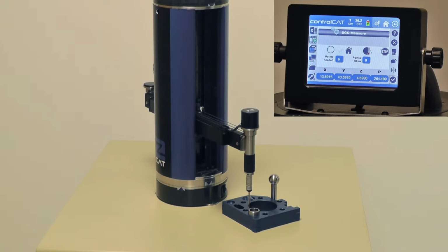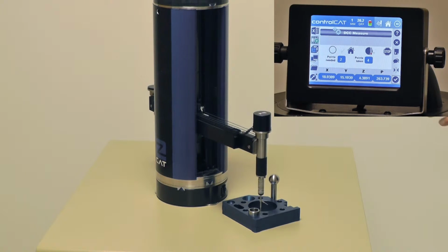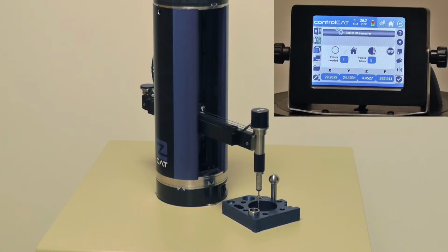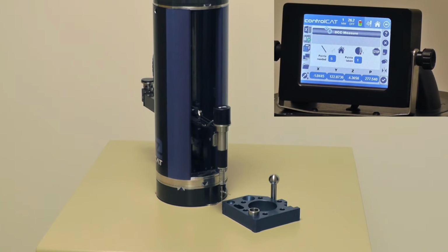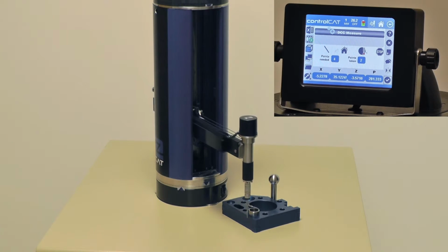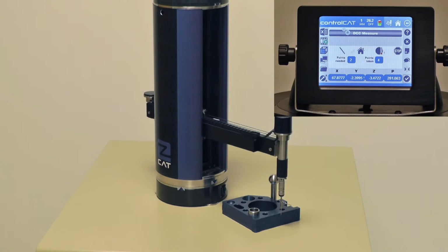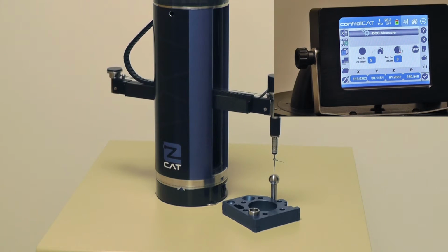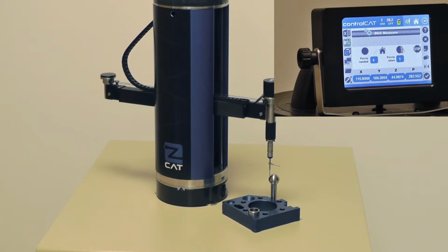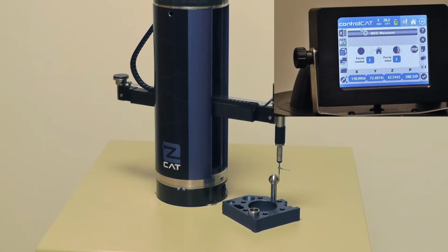So theoretically I could have multiple of the same parts ready to go. When it's finished with this part, I could bring the part number 2 down, put it in the same location, and run the same program and get the results from that part. That's if I had some kind of locating device, a fixture, locating pins, something like that. Or if I just randomly put the part down somewhere, I could do a new alignment, tell the gauge where that part is, and then run it again, and it will know exactly where that part is and all these dimensions are and give us the results from each one.